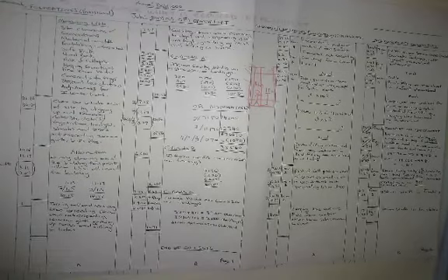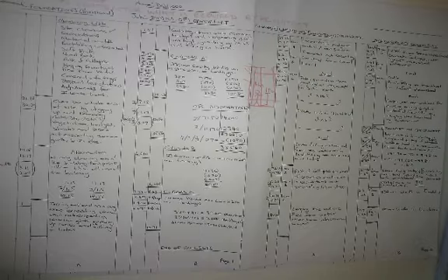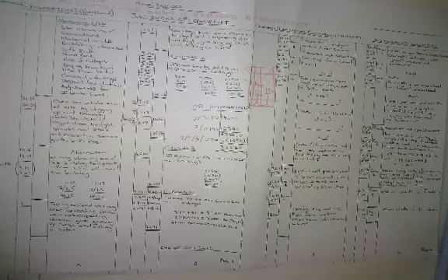I think now all of you are familiar with our descriptions. This description, you will use it up to your 4th year. You as a contractor need to state it so clear that there's no ambiguity. So we say clear the whole area of the site by digging up and removing rubbish, debris, vegetation, hedges, shrubs, and trees not exceeding 200 millimeter depth.